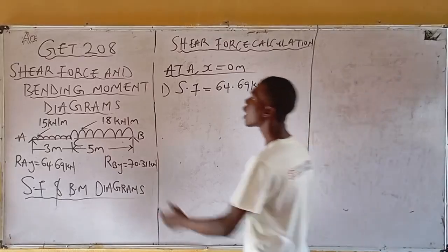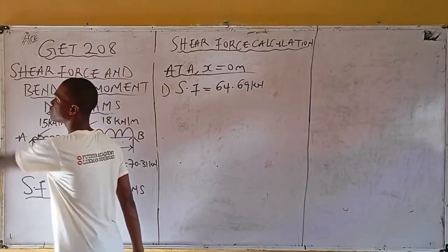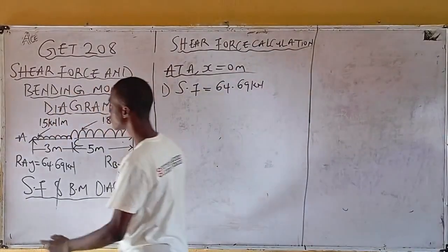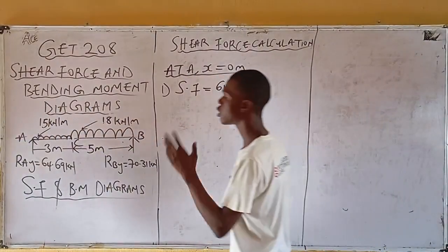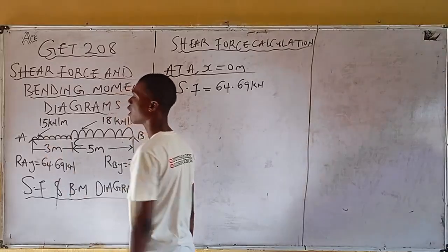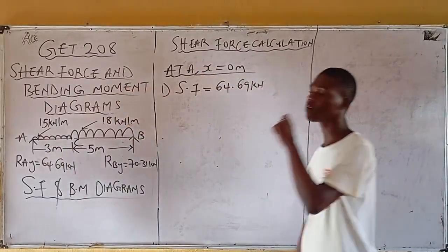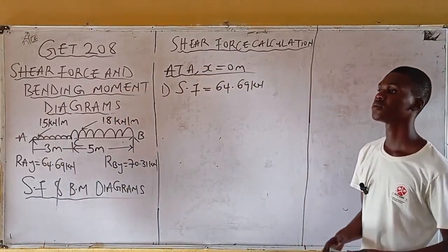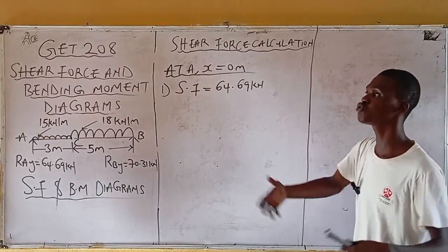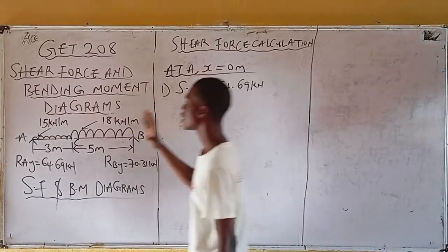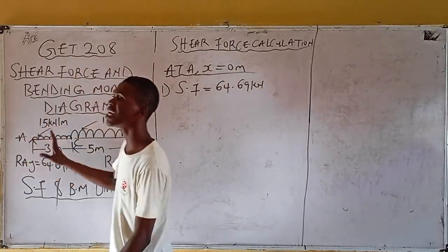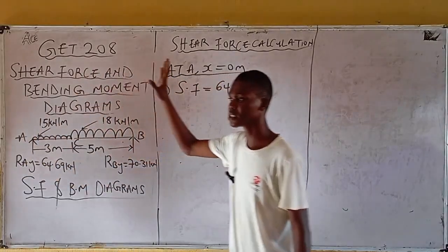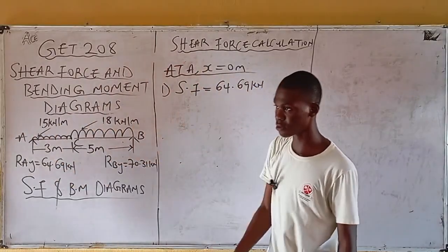Alright, now I'm on point A. Do I have any forces behind? No forces behind. So that condition is not satisfied on point A. Number two, value of shear force is what? Combination of the algebraic. Okay, let's assume that since there's no force behind A, let's assume all the forces that do not exist to be 0, right?